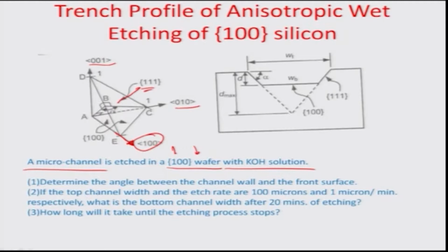The 111 plane is in this direction, as you know, this is the 111 direction and the plane is perpendicular to it, and the plane which is 100 is actually perpendicular to 100. So it is about a dot product of these two vectors together, which would give you an idea of what is the effective angle which would get formulated with respect to the principal 100 direction, which is the growth direction of the crystal in this particular case, okay.